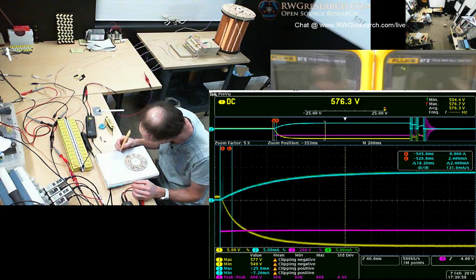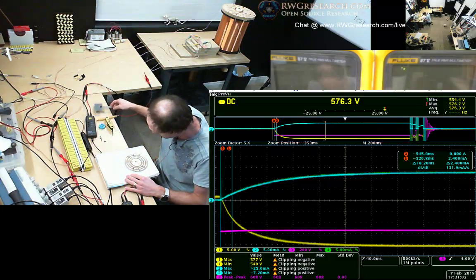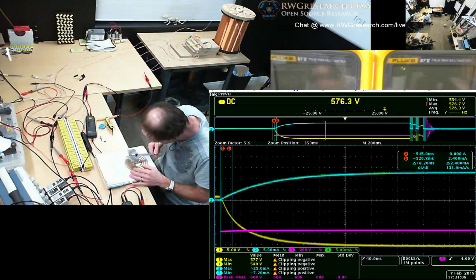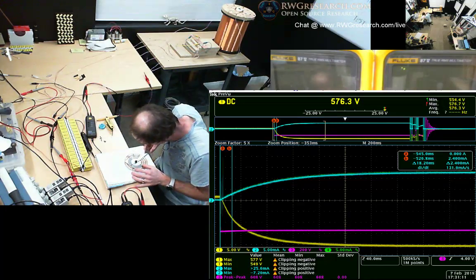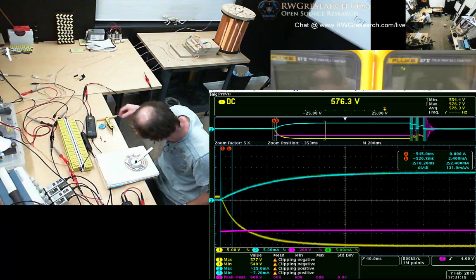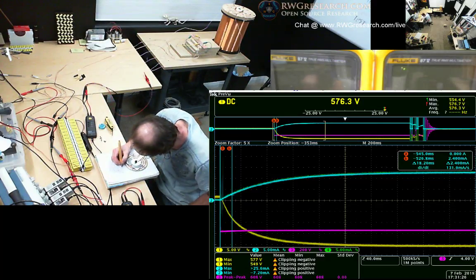Okay, Richard, what? Six pieces, buddy. The 110 degrees needs to be cut into 6 pieces. Let's see, yeah, it's right at 110. So if I have 110 and I want 12 degree segments, 12 on and 6 off, it'll divide equally into 6 pieces. Yeah, but we want 12. Oh, so 12 degrees on, 6 degrees off. Right. That gives you 18 degrees.